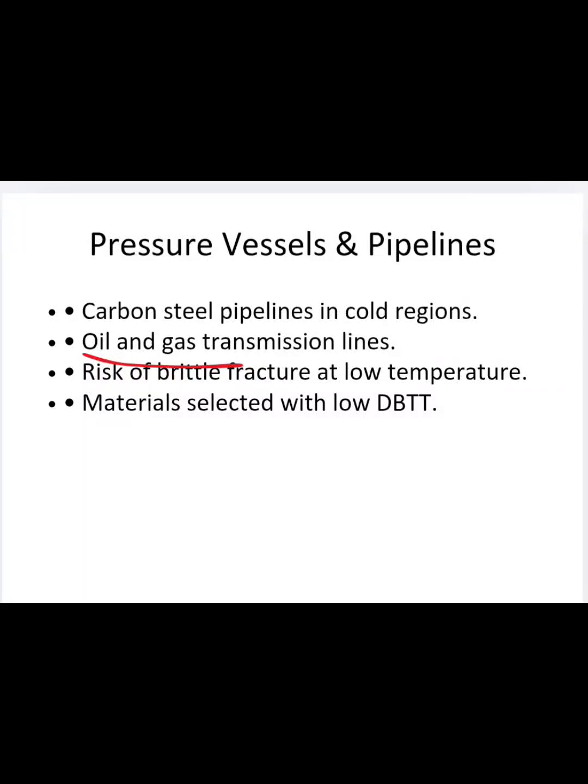In cold regions, the operating temperature may approach or fall below the DBTT. If this happens, the material may fracture suddenly under internal pressure. So we can use materials with a low DBTT.